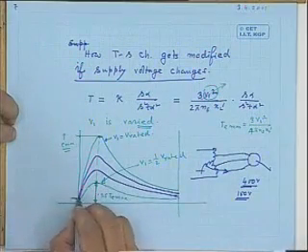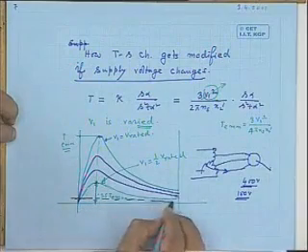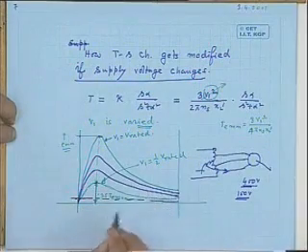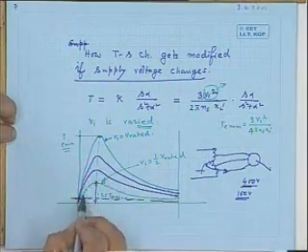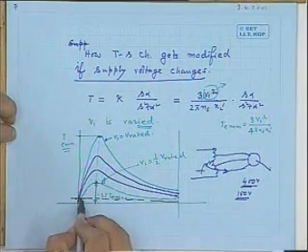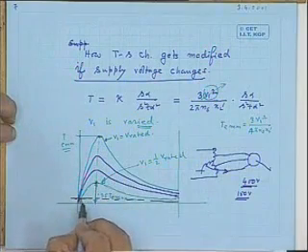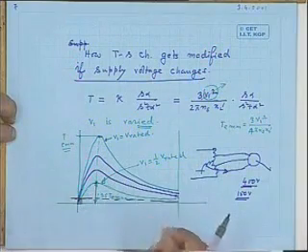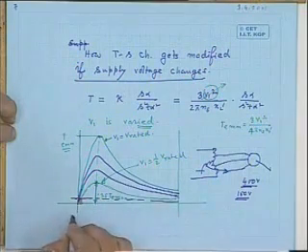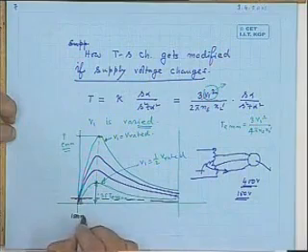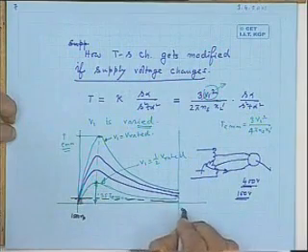This should not surprise us because the frictional torque present on the shaft of the machine may be quite low, like this. So no matter whether the voltage is rated or half this value, the speed variation of these two is quite small. Are you getting? Suppose it is a 4-pole machine.